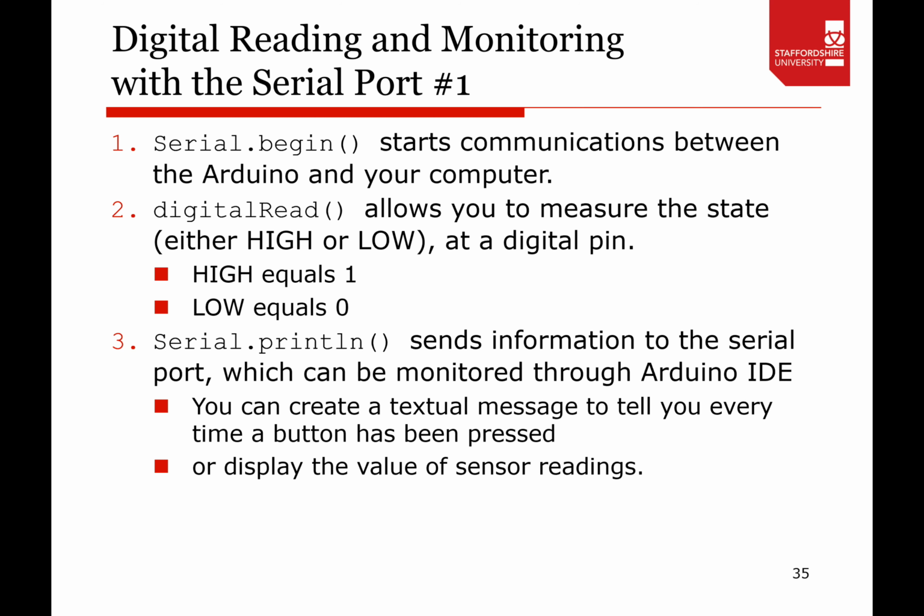So here's the next example: digital reading and monitoring with the serial port. These are the functions that we are going to use in this second program. Serial.begin. Serial, as I mentioned in the first part, is a library.